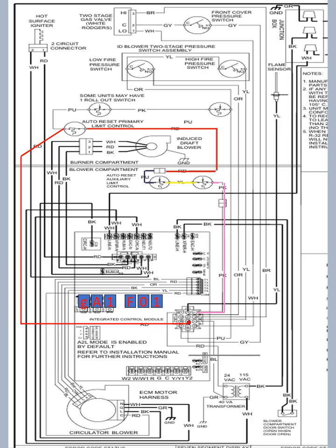And the red wire, why is that going back to the 12-pin connector? That's the step that proves that those three switches are closed, because we're in the pre-check phase and the board wants to see that those switches are closed.